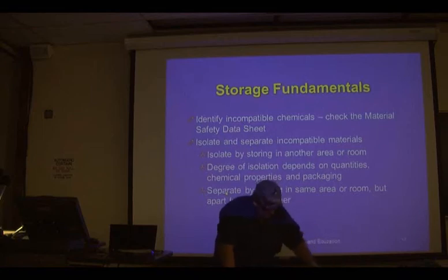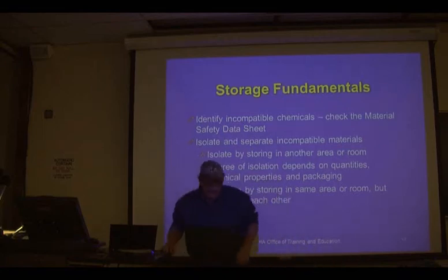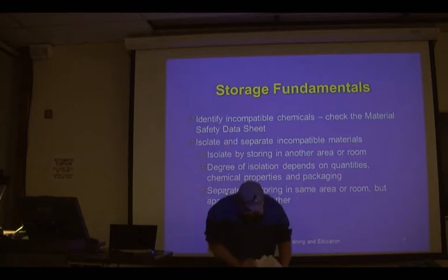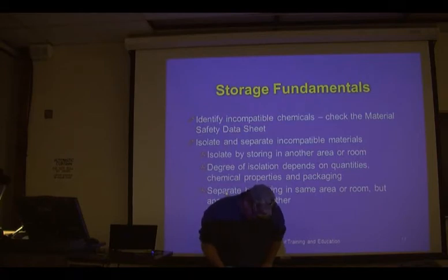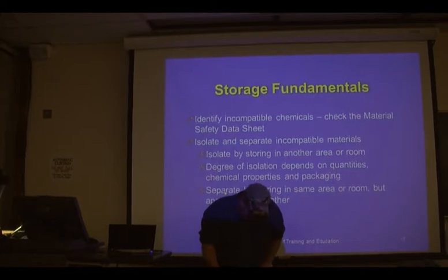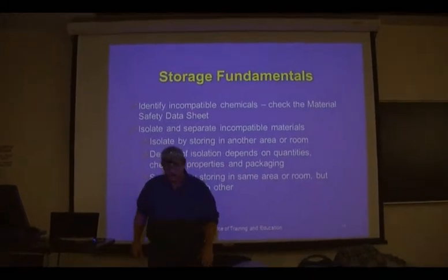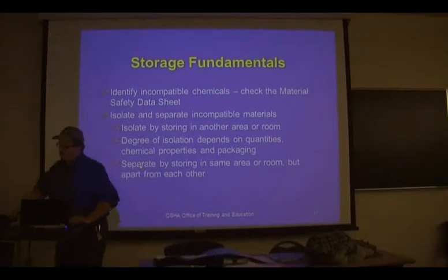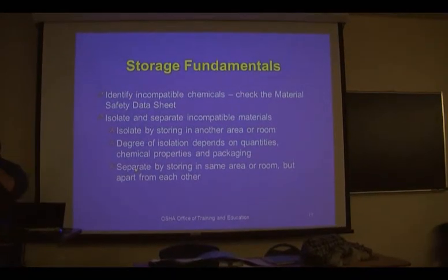Oh yeah, you did. Number 6 on the back. Number 6, list the ventilation requirements. Reduces potential for ignition of flammable vapors by preventing buildup. Must be sufficient to prevent accumulation of significant quantities of vapor-air mixtures in concentration over 1/4 of the lower flammable limit. So you've got to have enough to keep it from accumulating.